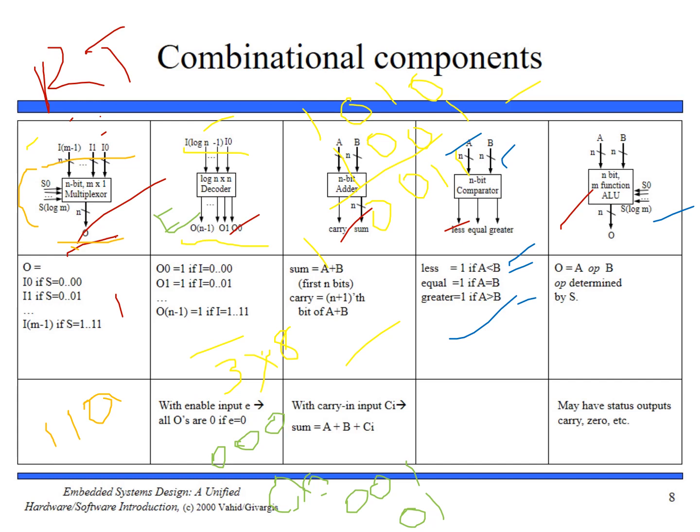Now, how can we perform this? You can see there are select lines. It means that a mux is there. So if we have select line 0, 0, 0, or for example, if it was performing 8 different operations, so we need to have 3 select lines. Okay. So for example, on 0, 0, 0 it performs addition, on 0, 0, 1 it performs, let's say, subtraction, on 0, 1, 0 it performs AND operation, and on some other select line it performs OR operation.